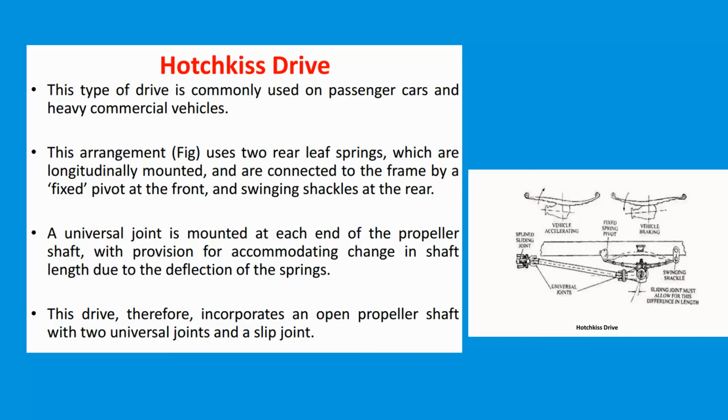In Hotchkiss drive, slip splines eliminate thrust transmitting back up the drive shaft from the axle, allowing simple rear axle position using parallel leaf springs. In the torque tube type, this thrust is taken by the torque tube to the transmission and hence to the motor mounted on the frame.